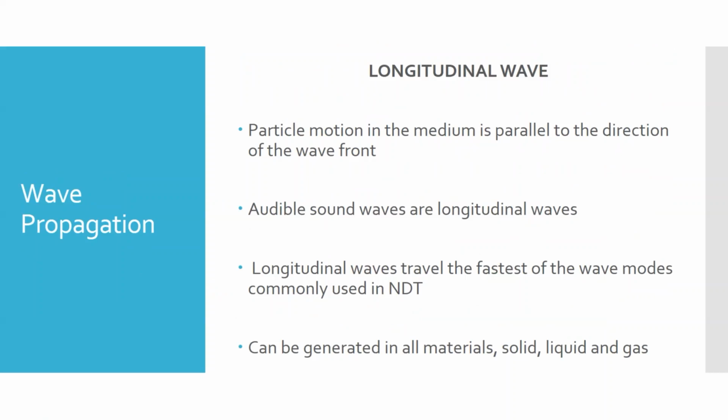We can submerge a part in water or liquid or oil, and we can send the sound wave through the oil and eventually into the part without ever touching it. Or there's even, I've got a video where they have an ultrasonic tester. It goes around the part and it shoots a jet of water onto the surface of the part.